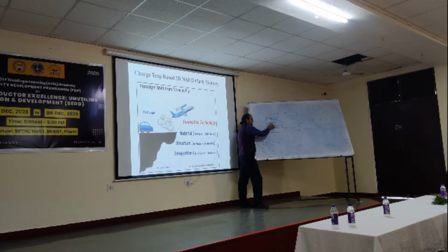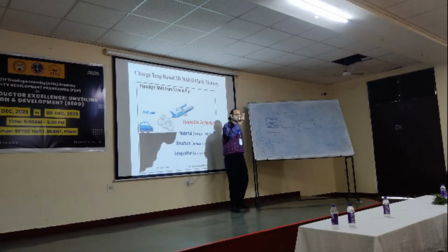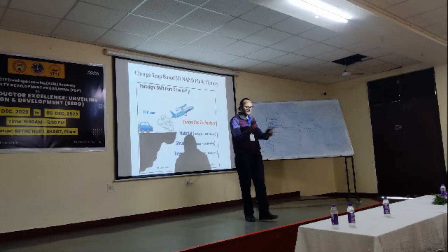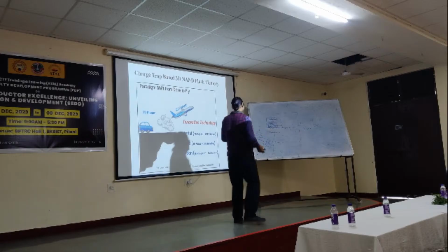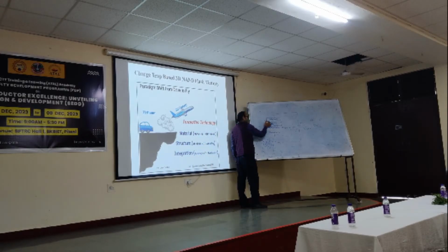And now you see, if all the voltages are removed, what will happen? This electron will stay there even for 10 years. There is no way of leaving it. It will not get released either up or down. Why? Because we have insulator here. Here we have insulator, but it is trapped here. So that is how this comes into use as a memory element.